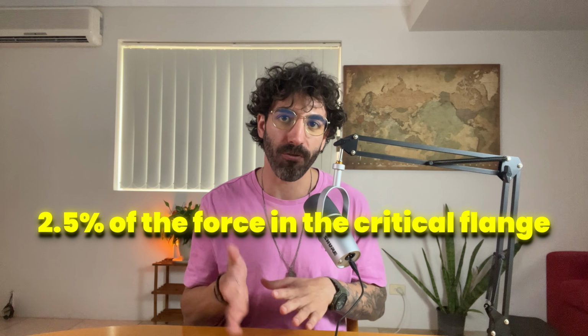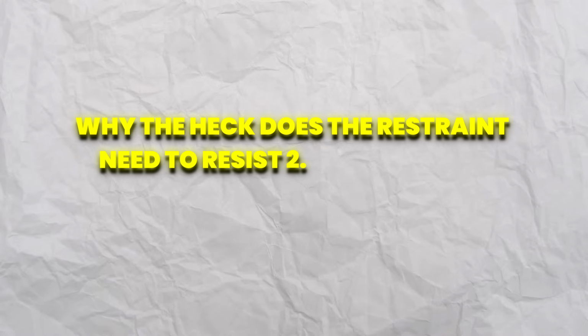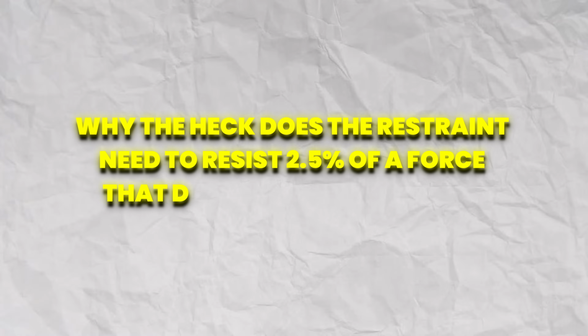As a general rule, a restraint has sufficient stiffness if it can resist 2.5% of the force in the critical flange. Now you might be wondering, why the heck does the restraint need to resist 2.5% of a force that doesn't even go into it? Well, my friend, I have no idea. Nah, just kidding. I'll never leave you hanging. The answer has nothing to do with strength.